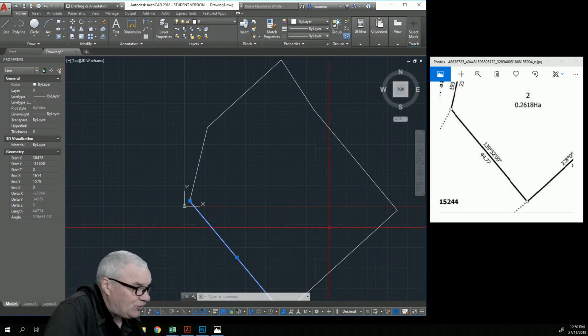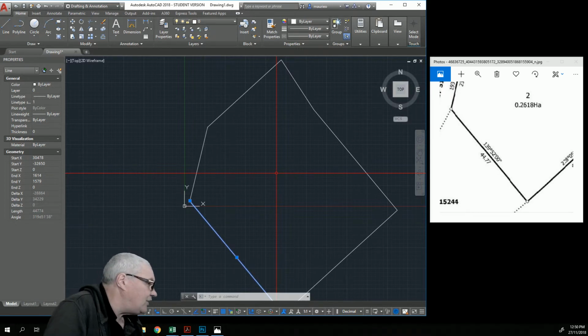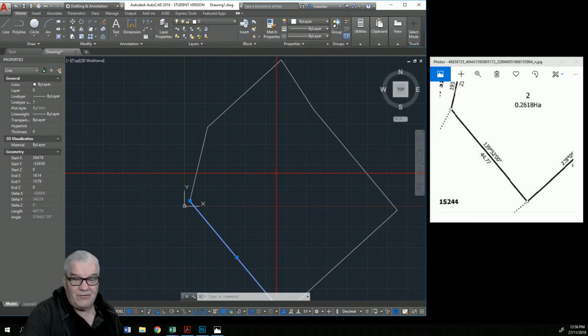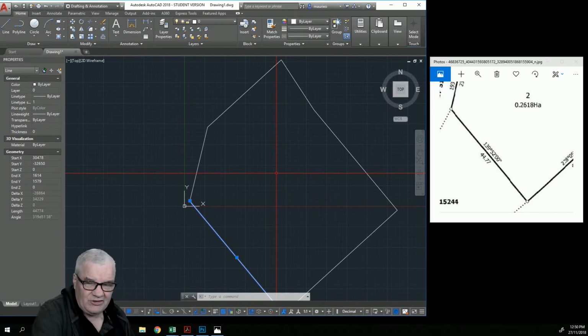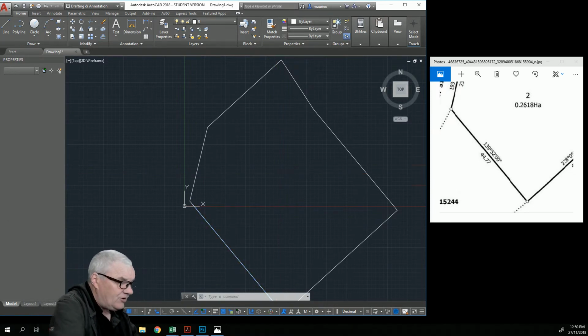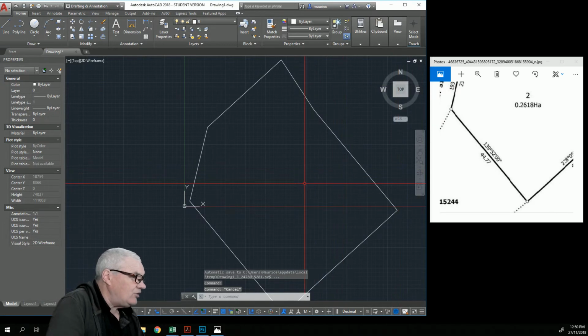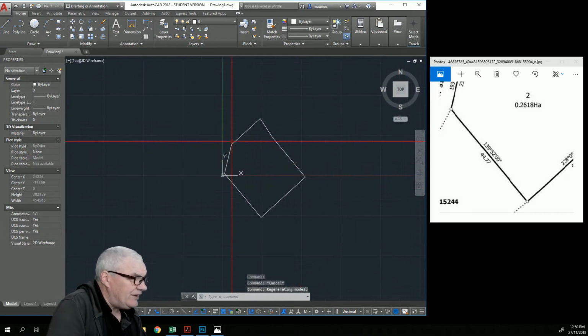Okay, and for the distance, we've got 4477.4, so we're 4 millimeters out for distance, and in about 22 seconds, whatever the tan of 22 seconds times 45, it's about that. So that's pretty good. So that's it there. That's your closed figure there.